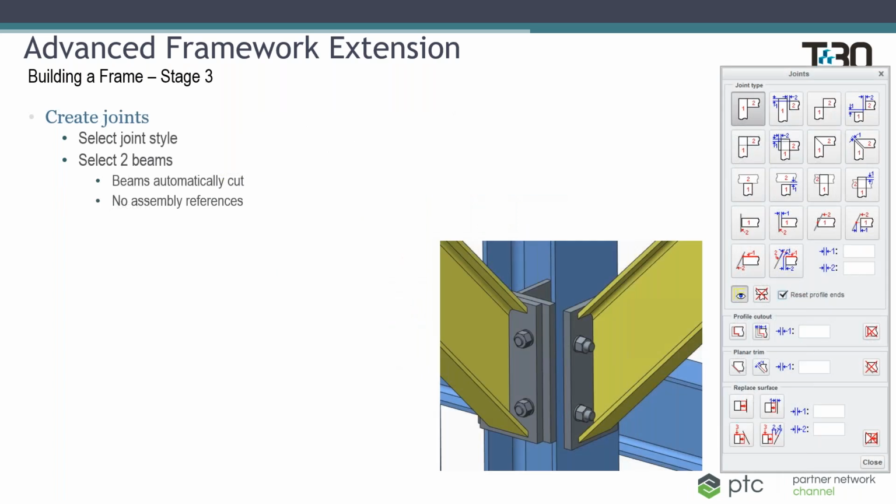Okay, so once you go ahead and decide what beams you're going to use, all you have to do is really select those curves that you created in the sketch environment. And we'll touch on that in the demo, but here I just want to show that once you go ahead and place those beams, the next thing you'll want to work on is those joints. So how those beams integrate or connect to one another. And so you'll have to create those cuts.